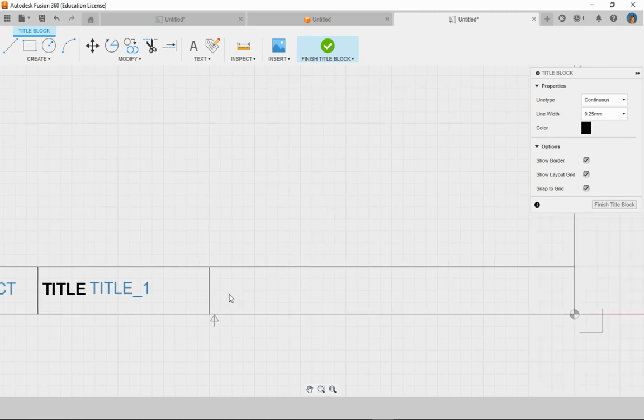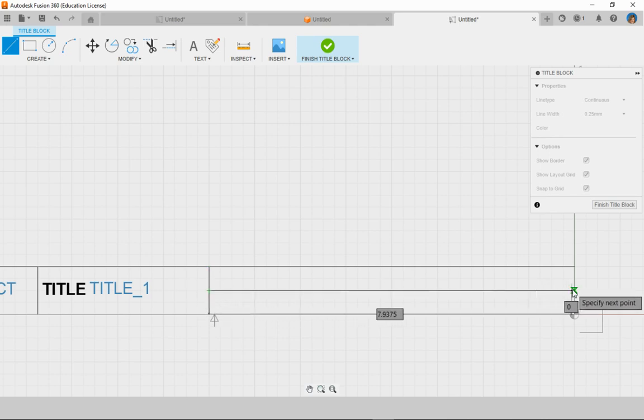Now before I move on, I'm going to draw another line that's going to divide this area in half. So I'm going to go up to my line tool. And this we did when we were doing the constraints. Now follow this line down until I find my midpoint, which if you remember is that triangle. So click, I drag all the way across, and click on that side, and OK.